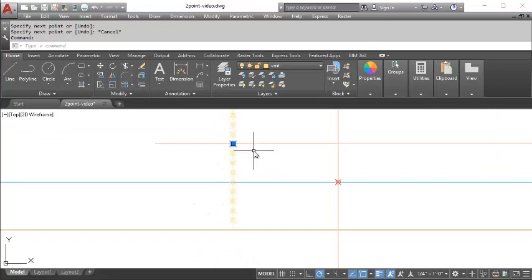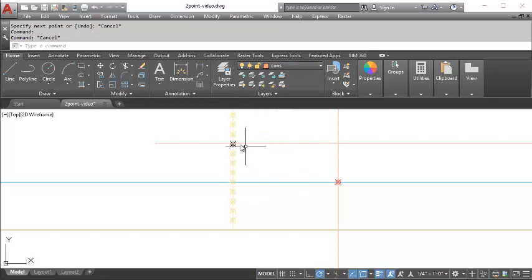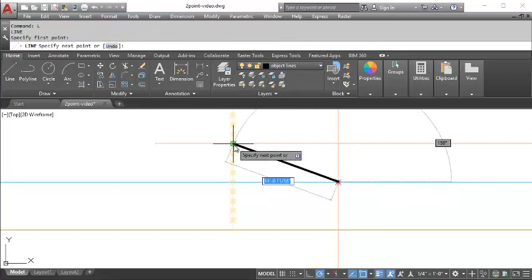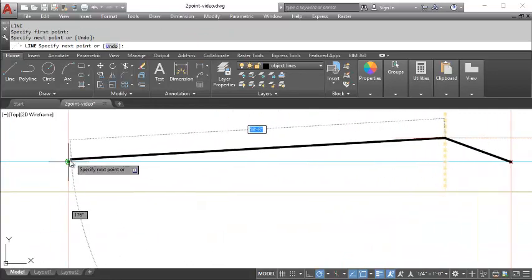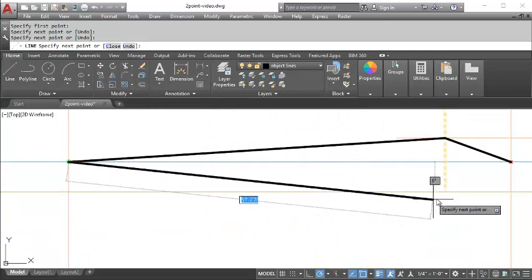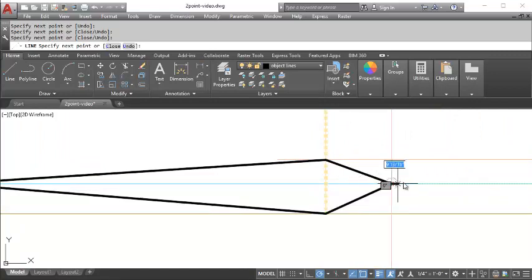So I'm going to use an object line and go from, whoops, I didn't mean to change that to an object line. So let's switch to an object layer and create a line from my vanishing point right through that node, and then I'm going to go all the way over to my vanishing point left, and then go to the base of the building, and then back over to my vanishing point right. So this is defining the top of the wall, bottom of the wall on the right side of the building, top of wall, bottom of wall on the left side of the building.